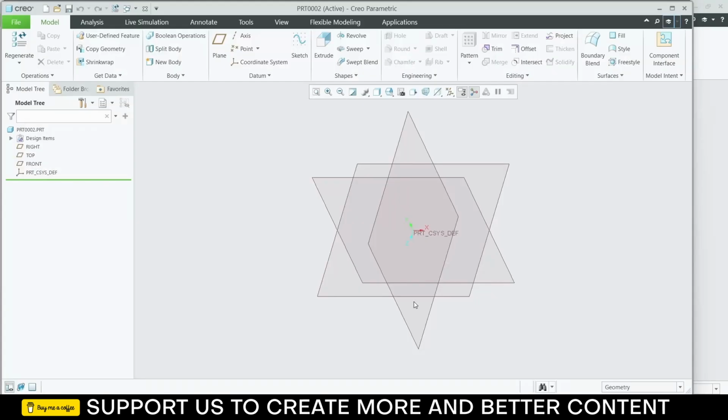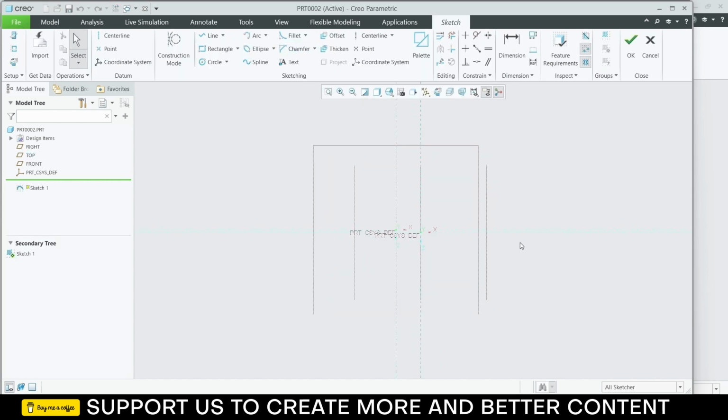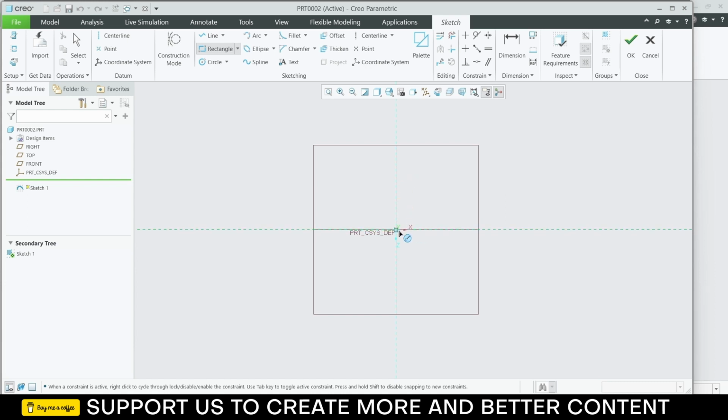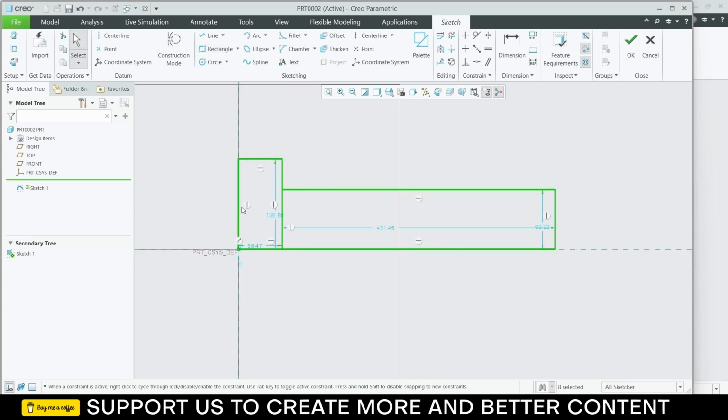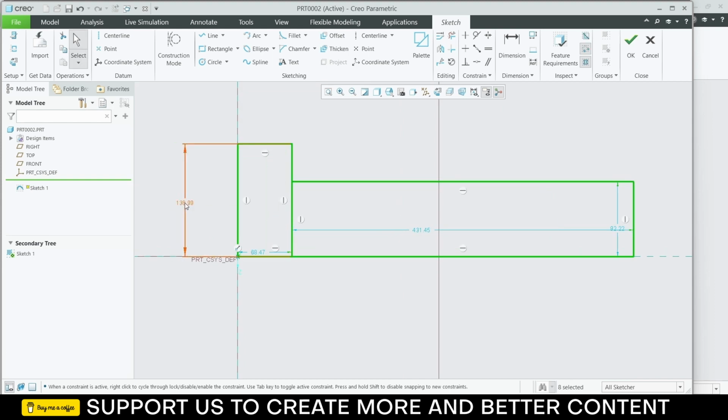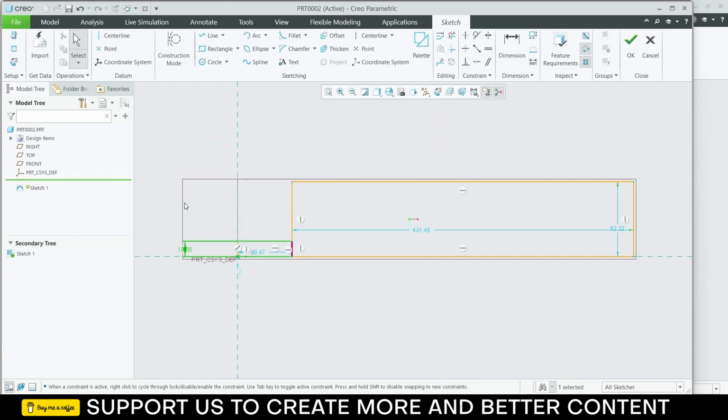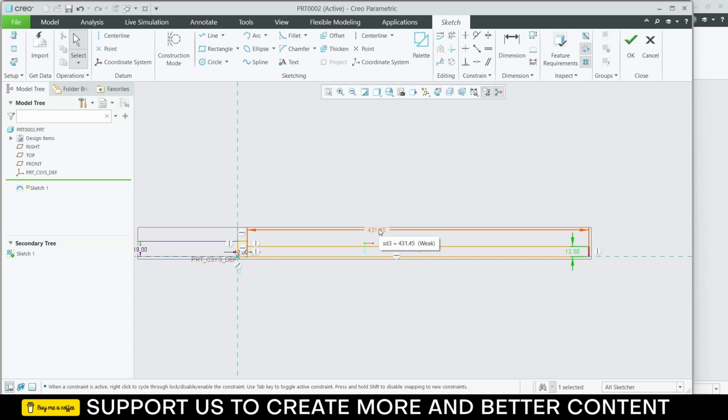Okay. Select this. Now move to the screen. Sketch. Click on triangle and click on the middle mouse button. So this will be 38 divided by 2, and this will be 12. This will be 25 divided by 2, and the length will be 90.